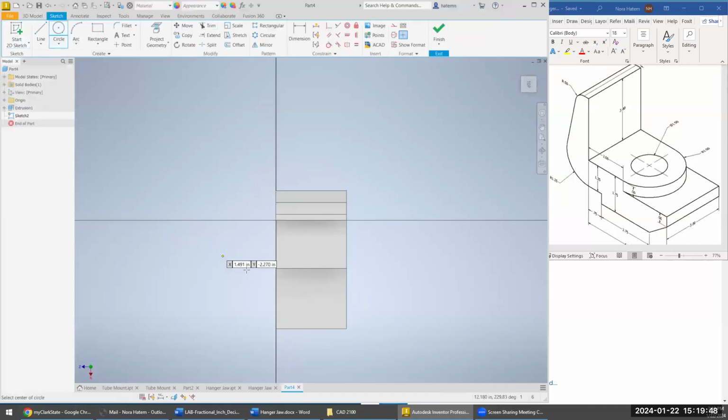So I'm going to go ahead and select my circle, and all I'm going to do is find my midpoint. So see how it locks to that midpoint, stretch my cursor off till it locks to that endpoint, and it's fully constrained. So now if that 3 inches becomes 4 inches, this circle will go ahead and automatically edit. And then we're going to put our hole in using the same center point or midpoint. And this is 1.5, it looks like. And notice again, it's fully constrained because it's off that midpoint.